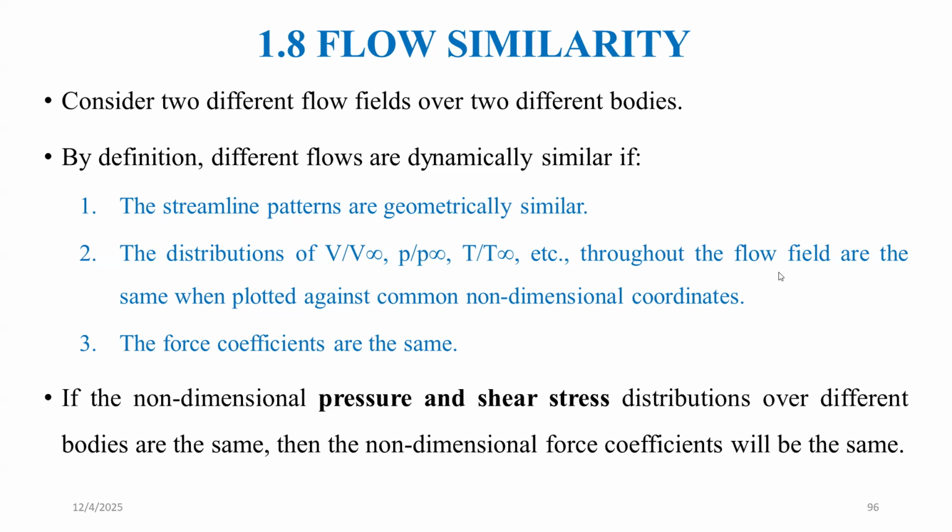So if the non-dimensional pressure and shear stress distributions over different bodies are the same, then the non-dimensional force coefficients will also be the same. That's why flow similarity will help us to model a small prototype model of large, huge aircraft and other space vehicles.